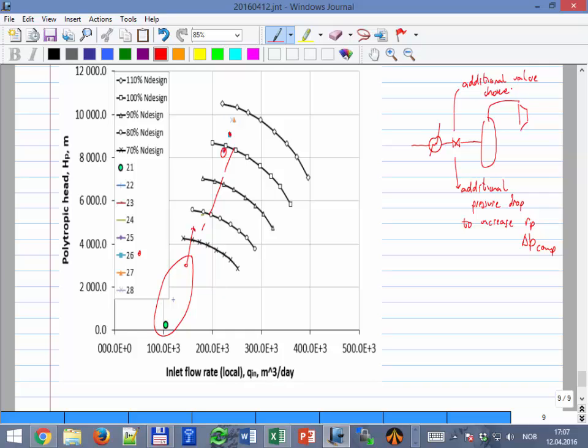We want to reduce the pressure at the inlet, so the compressor has to give more delta P. And really that's not very intelligent to do, because we are removing pressure to add pressure, but it's only to allow the compressor to operate properly, to put the points inside the operational map. But the rest looks okay. Now the trend, I don't know if that's correct or not, maybe we have made a mistake, but we have to find what's the reason.